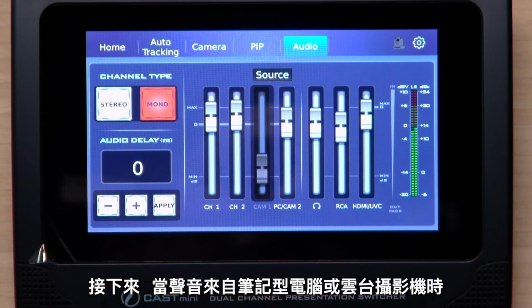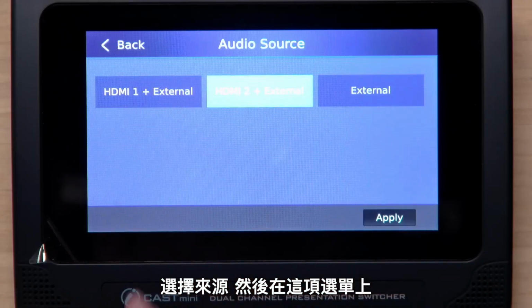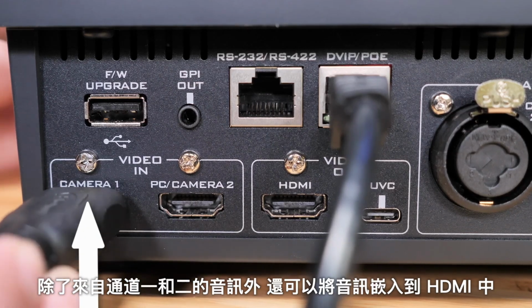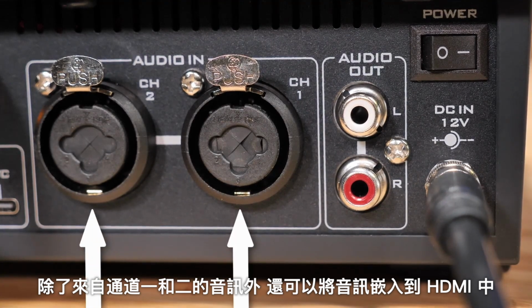Next, to have audio come in from a laptop or PTZ camera, select Source, and in this menu you can choose to have HDMI 1 plus external, which would have audio embedded in the HDMI signal, in addition to the external audio, which is from channels 1 and 2.